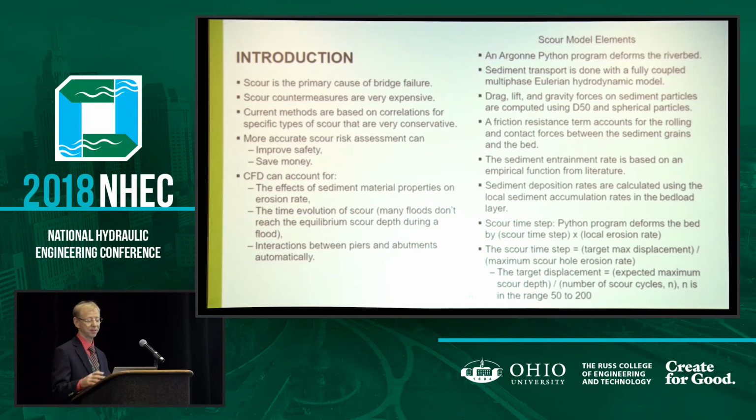And there's nothing really stopping us from using a size spectrum of particles. So you just discretize the spectrum. You can use like 10 size groups. I've done that for various spray type calculations and it works well. And you'd end up with 40 equations to solve in the solver. And that doesn't put a big strain on it; it extends your time, of course, but not that much, so it's good.